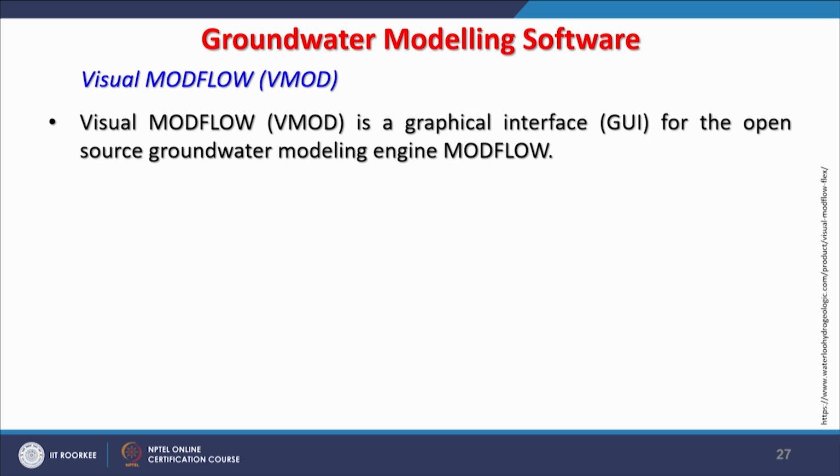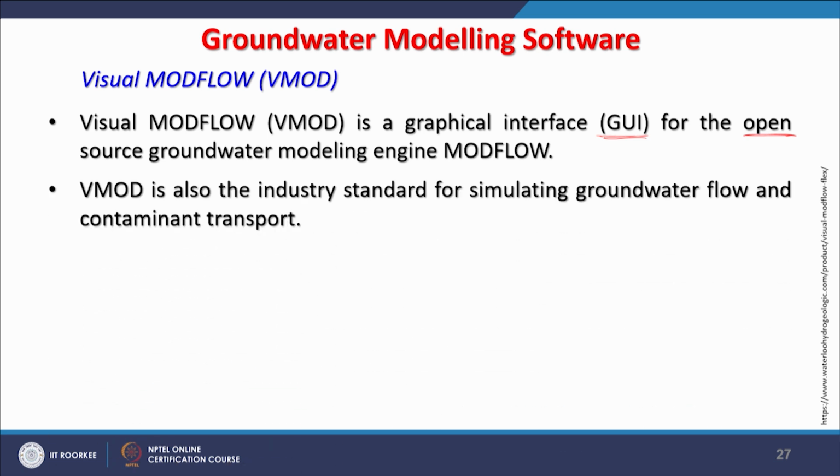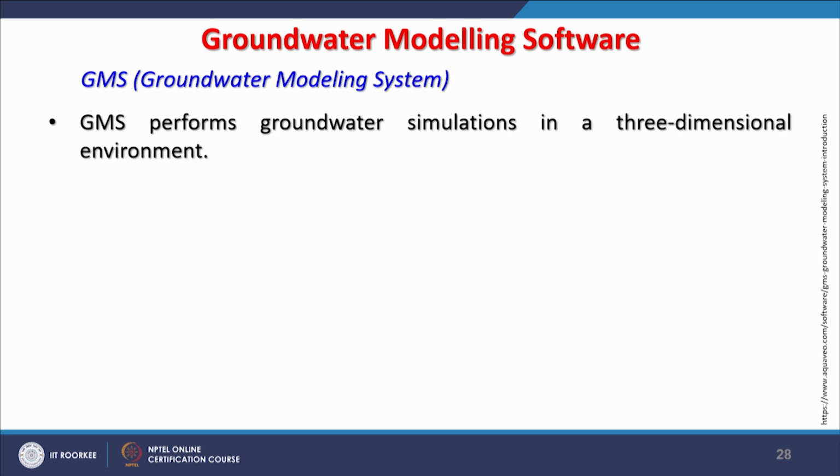Visual MODFLOW or VMOD. So, Visual MODFLOW is a graphical interface. You have a GUI, so it becomes much easier for the user to provide the data, and an important part here is that it uses an open source groundwater modeling engine. So, in that way no cost is involved since it is open source. VMOD is also the industry standard for the same purpose, simulating groundwater flow and contaminant transport. So, in case of pollution studies this can be used successfully.